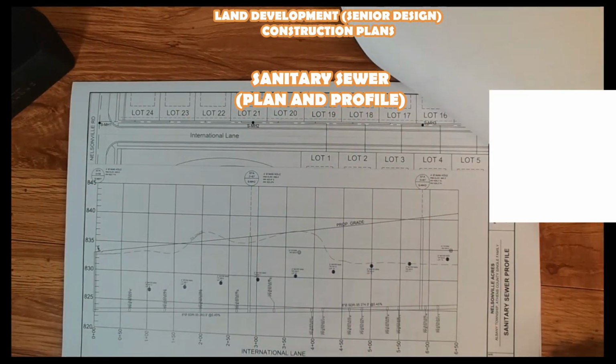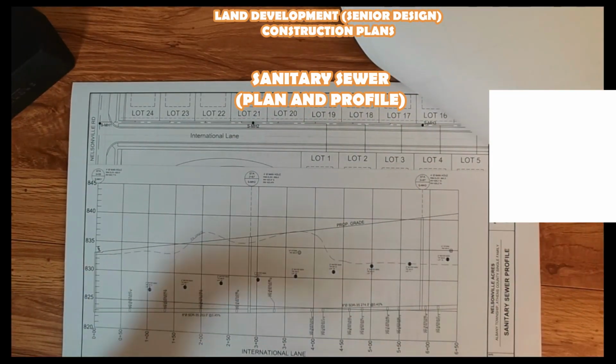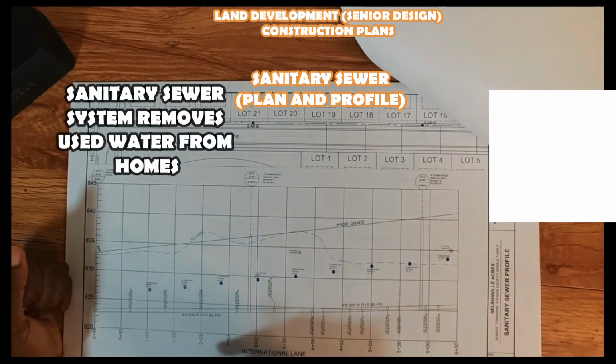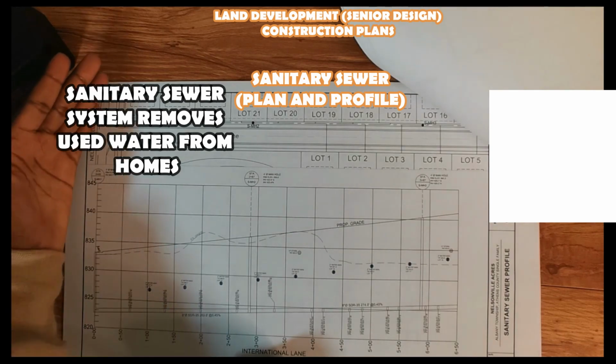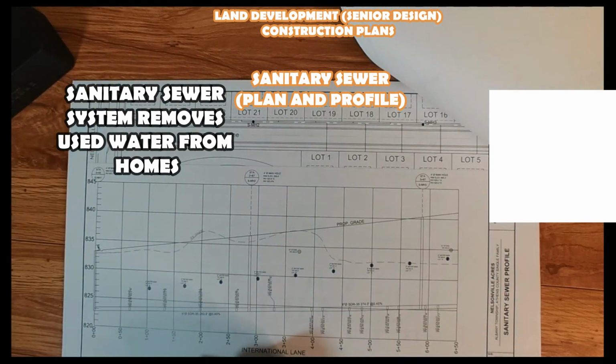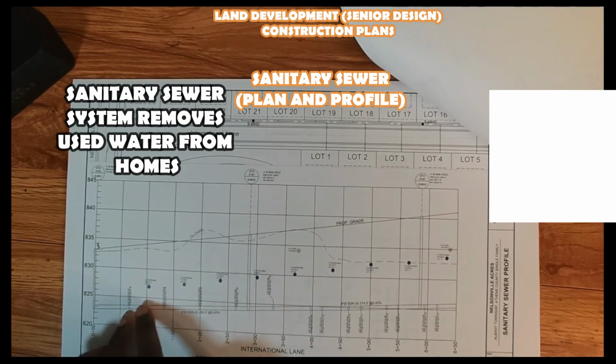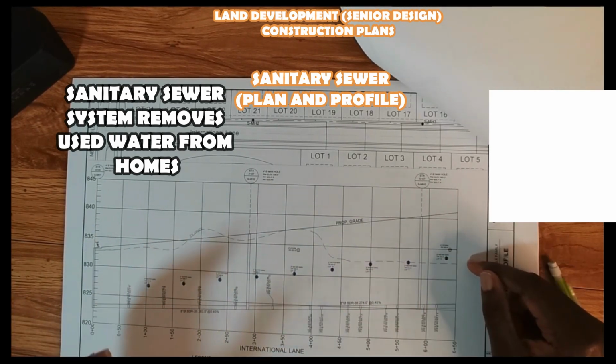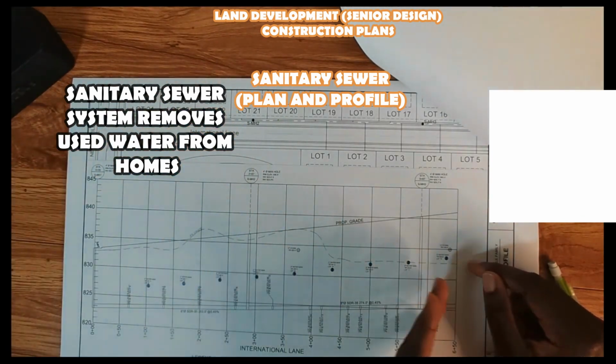Now what you're looking at is the plan and profile for the sanitary sewer. As I mentioned, the sanitary sewer is the water that is being removed from the homes. When you go to the bathroom or shower, the water that you've used needs to be removed, and that's getting removed through the sanitary sewer. This is the pipeline for that. This little dot up here is a connection to these homes and the different lots.